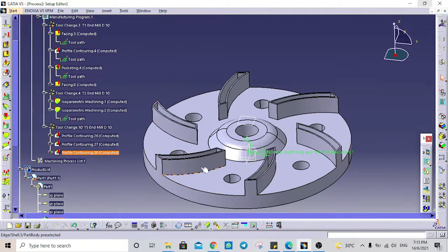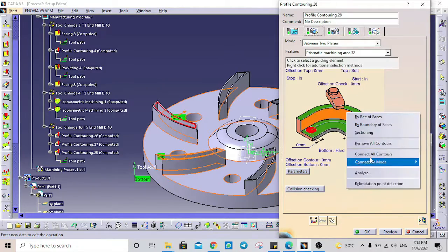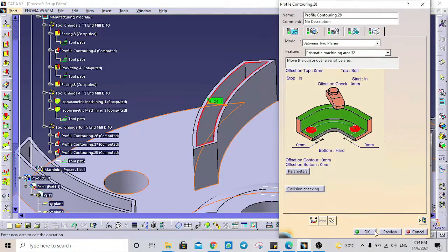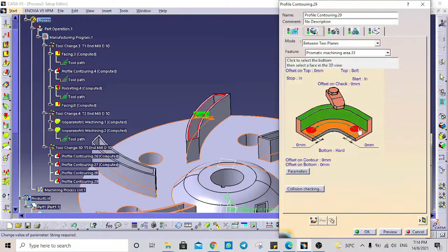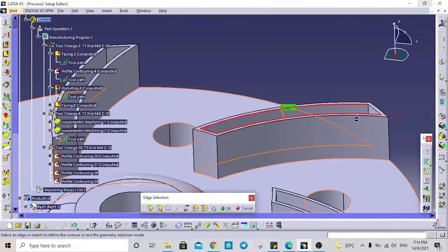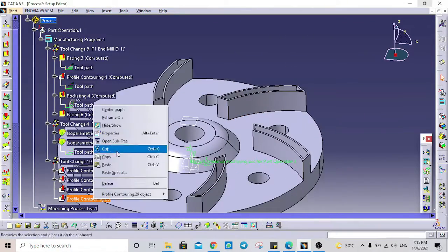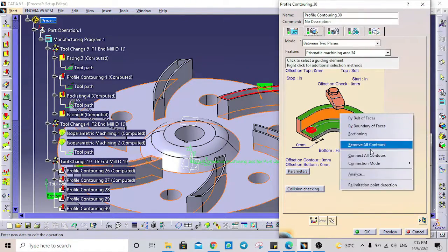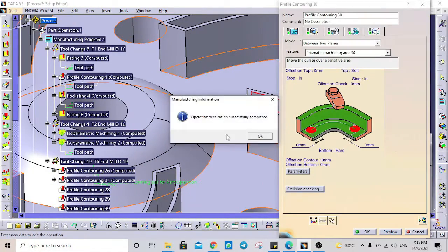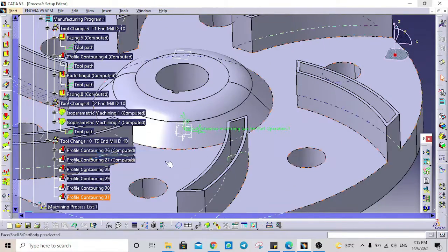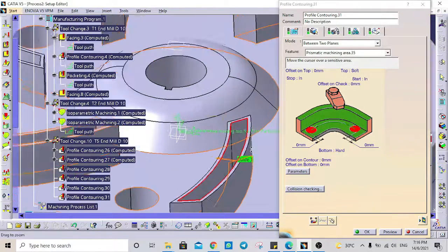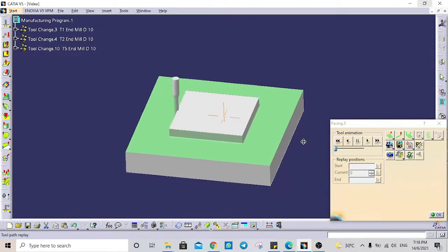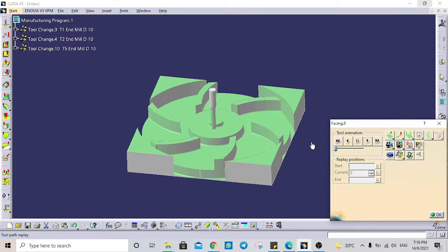After done second blade shell, now we can proceed to the third shell. By using the same parameter and same top plane and bottom plane of second blade shell, we can copy the parameter of the second blade shell into the other blade shells. The difference of the parameter are only on the side or guide plane. Then after done, change the parameter of the third shell, fourth shell, fifth shell and sixth shell. Now we can run the simulation for all 6 blade shell.